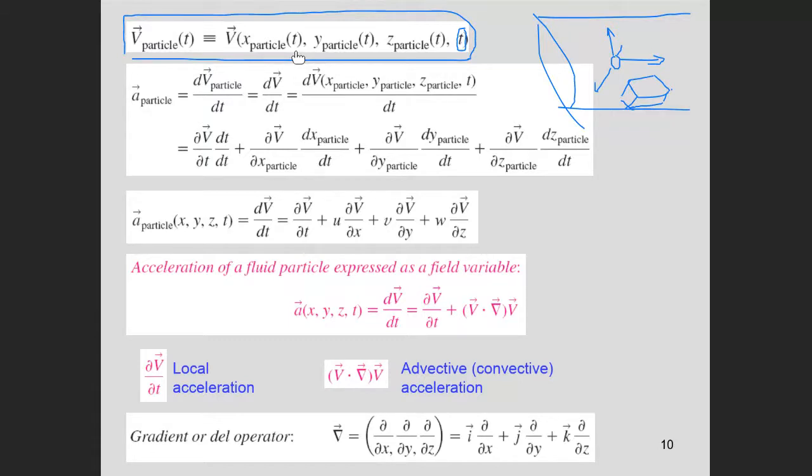In spray combustion alone, you have to use a few millions, like 10, 20 million particles, in order to get a good representation of the flow. That is why Lagrangian is very difficult. But the other one, you can divide into small volume or large volume, so it is doable. It is cheap, not expensive, the Eulerian approach.